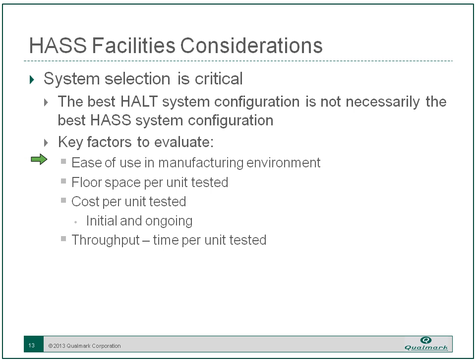Key things you need to look at. Am I going to be able to fit this into my manufacturing environment and use it easily? There's doors on these that open out, and once you get both doors open, there's a lot of floor space involved. Look at numbers like floor space per unit tested and cost per unit tested, not only of implementation, but of utilities as an ongoing cost.